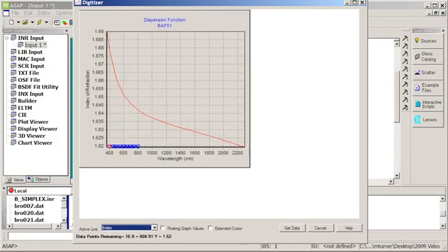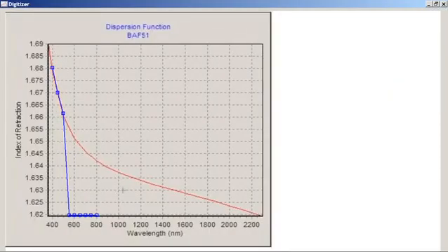And you'll notice I have a series of little markers here that I will simply move. They're fixed in the wavelength or the X direction, and all I have to do is drag them up to intersect the graph. And you'll notice they're hollow in the center, so it's very easy to see when I have the marker in the right location. I can also blow up the data and zoom in a little bit so I can get higher resolution. And I'm just going to move up my data points and just fit the curve as best as I can.